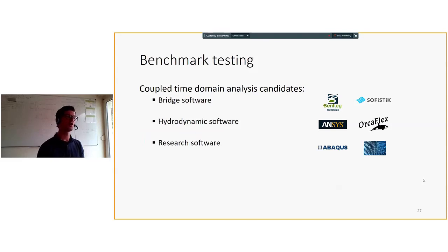But there are also other bridge software that are candidates. Sophistic also has a very good wind solution. My group also used OrcaFlex for some hydrodynamic simulations and time domain integrations. OrcaFlex already has all the hydrodynamic implementation, plus it has the possibility to convolute over the velocities. So it's a perfect candidate, for example, for this theory.